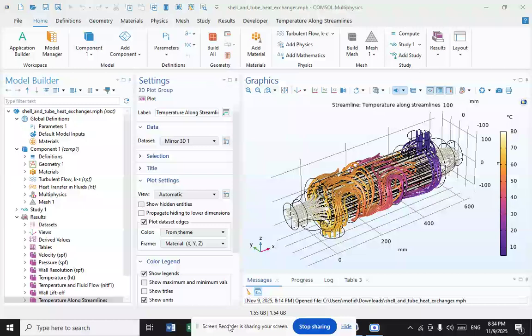The next one is tube layout. Refers to how tubes are positioned within the shell. There are four main types of tube layout, which are triangular 30-degree, rotated triangular 60-degree, square 90-degree, and rotated square 45-degree. The triangular patterns are employed to give greater heat transfer as they force the fluid to flow in a more turbulent fashion around the piping. Square patterns are employed where high fouling is experienced and cleaning is more regular.